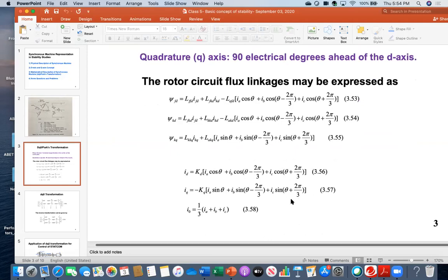It looks a little bit strange that I am concluding that a three-phase system is getting converted into only a two-axis system. Do you understand what I am saying? Is it not something strange that I am converting a three-phase system into only the two-axis component system, ID and IQ? That's why after developing these two relationships, the engineer Park said, no, let's write down